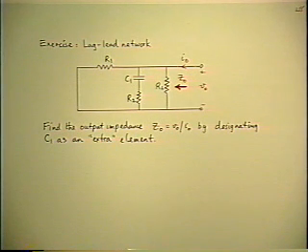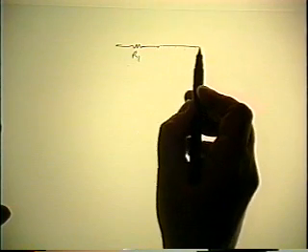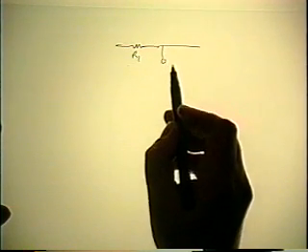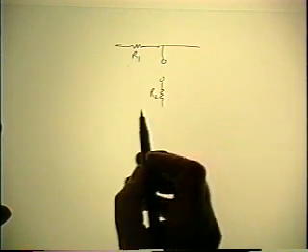Okay, I'll give you a few minutes to work on that, and then I'll go through the solution right away. Start with the reference circuit again, R1. Take the capacitor out and replace it with a short circuit.